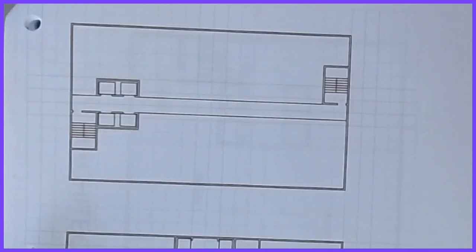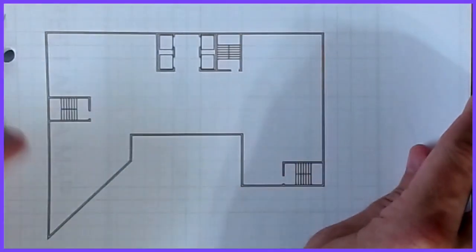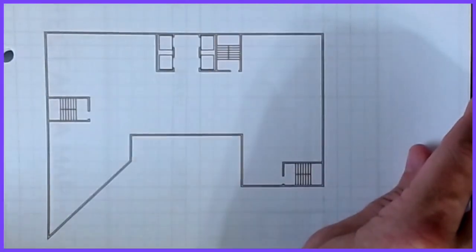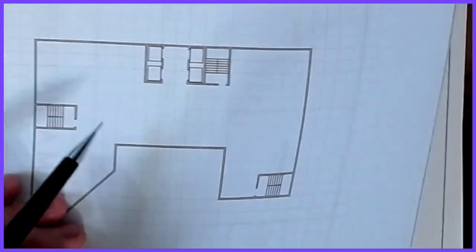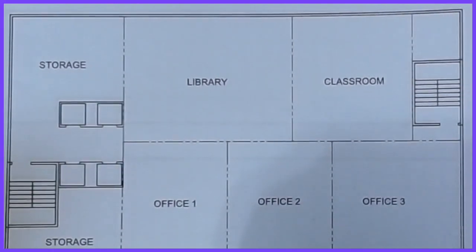We want to have a little bit of fun with it, right? So there's one with elevators and stairs, and then there's an irregular shaped one, and these are always fun to try to figure out. Where can I put columns? Where can't I put columns? And so forth and so on. So anyway, that's all we have to do. And then your homework, just so you have it, will be to do something: I'll give you an architectural plan that looks something like this, and you come up with a framing layout for that.